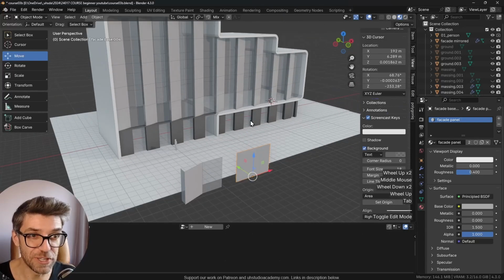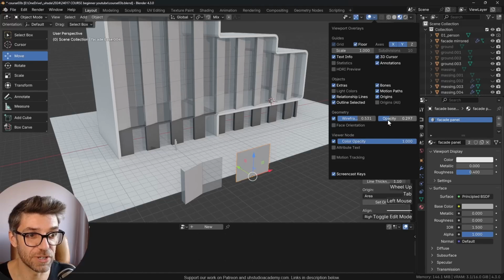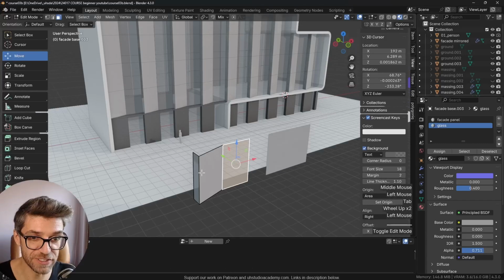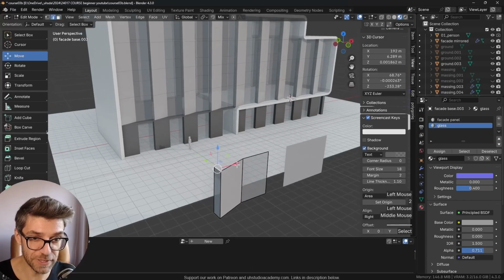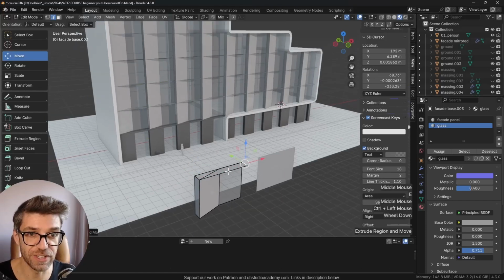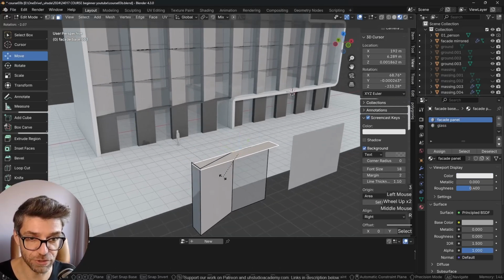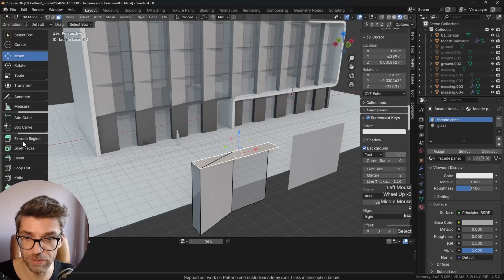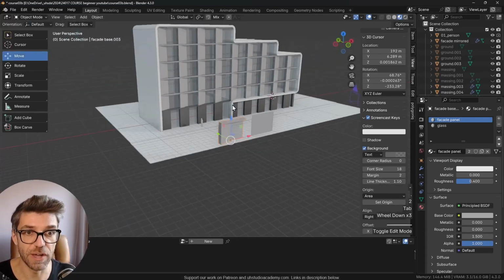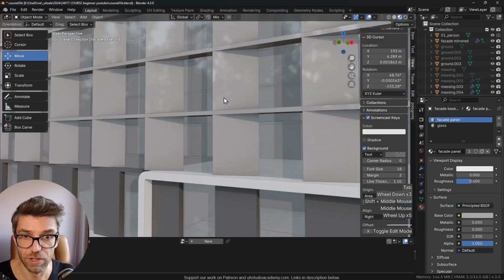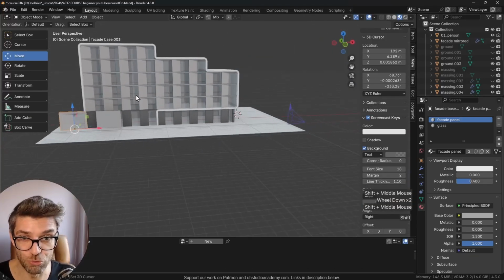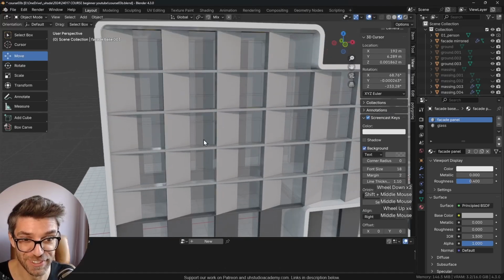So really cool thing is that now we have something that's very strongly vertical. But if you go back in here, I'm going to duplicate this edge, Shift D, and extrude it over on this side like that. And now I'm going to extrude this down. Let's use the extrude region tool and type in -0.2. And now we have something that's also horizontal. And wow, I mean, really, that looks really good for 2 minutes of work.